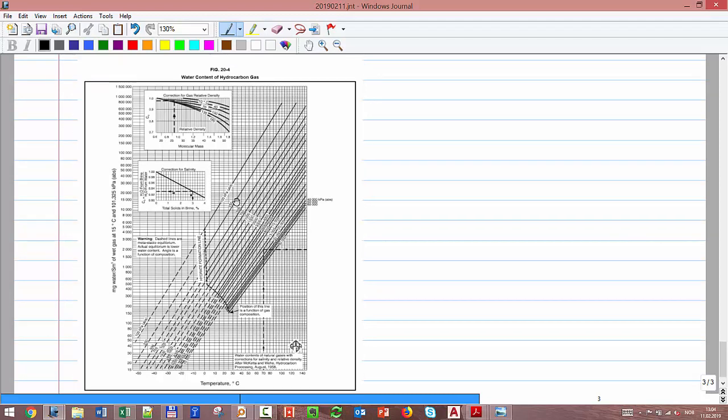Okay, so if you have RSW, that is standard cubic meter by standard cubic meter, how do I change it to the units that I have here, milligram per standard cubic meter? How do I change it? Simply RSW times the density of the water at standard conditions.